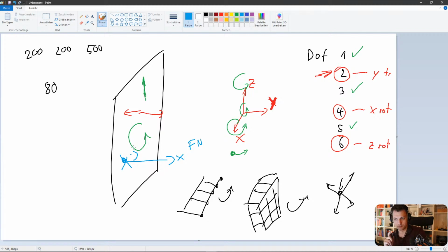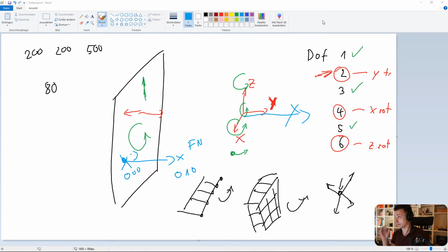And the anchor node, or the anchor coordinates, just show you where the symmetry plane is located. So origin gives location, and the first node gives direction. So what we did here was 0, 0, 0, that would be the origin. 0, 1, 0 would be 1 unit towards the y direction. So in this direction we had the 1. And that's the normal direction for a y normal symmetry plane. That's why we did it like this.